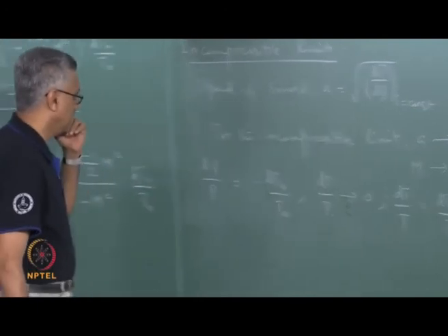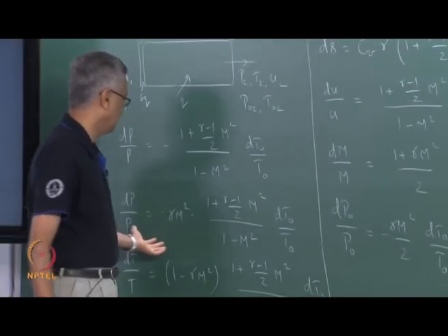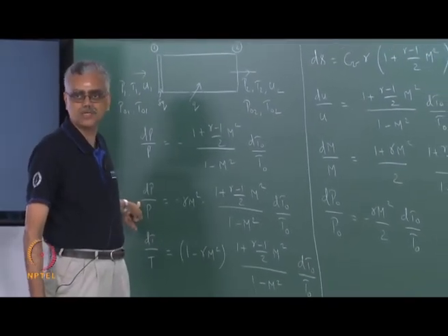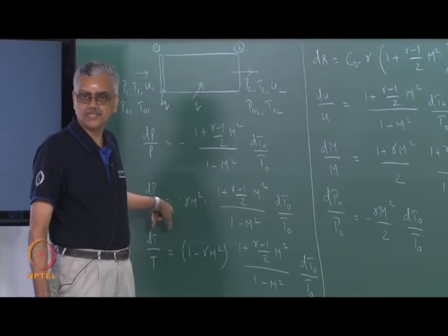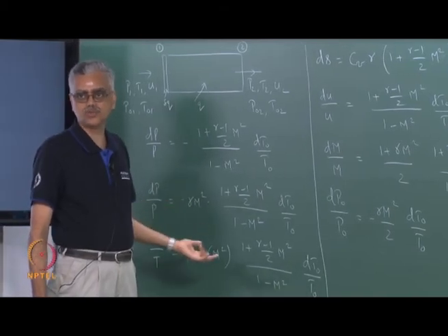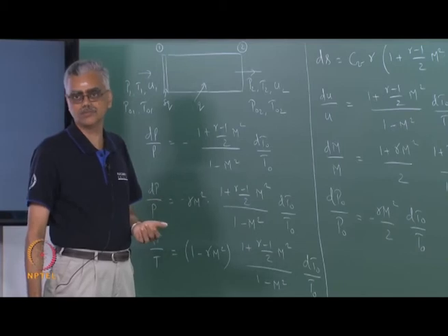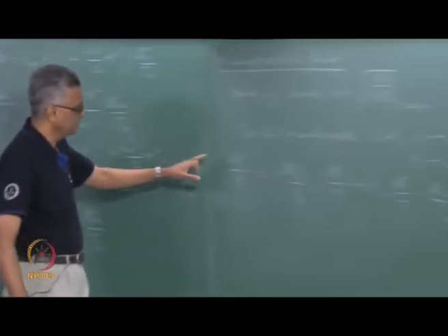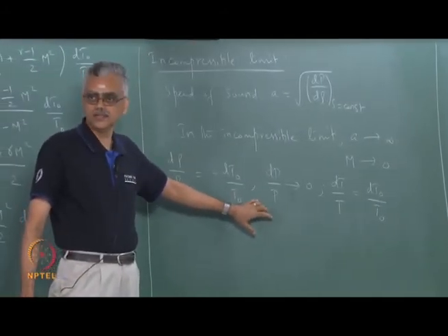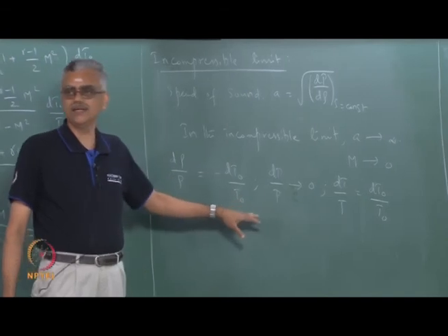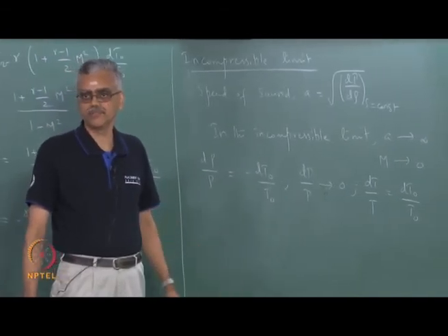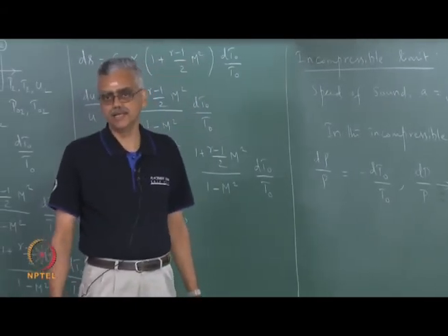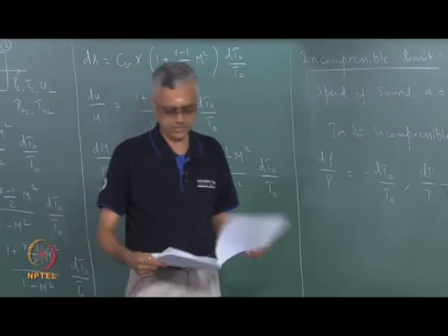And you also notice that if the flow is compressible and I add heat to the flow, then definitely there is going to be a change in pressure. Our TS diagram showed that, and we also know from this equation that the pressure is going to change, either increase in a supersonic situation or decrease in a subsonic situation. Okay. So this proves very clearly that what we said in our first lecture regarding compressibility can be proven mathematically also from the proper equations. Our next job is to transfer the information to a PV diagram in PV coordinates. That is what we are going to do next.